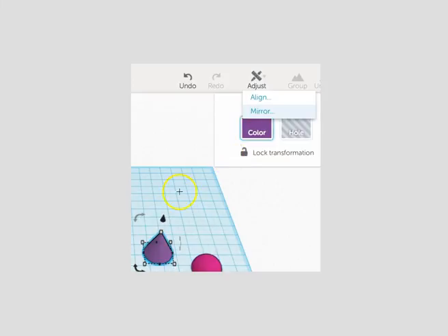And so then if I select any of the objects, what I see is that there are handles around it. These 4 handles on the bottom are to allow me to resize it in this horizontal plane. And then there is a handle up here that will allow me to stretch it in the vertical plane. And then this solid arrow here allows me to move something up and down. And then there are rotation handles that I'll show you the use of here shortly.